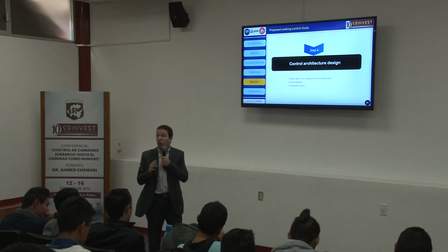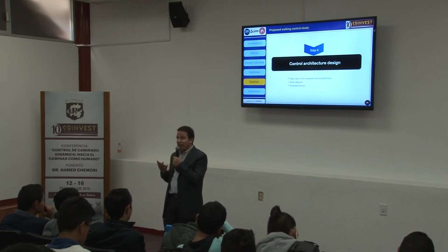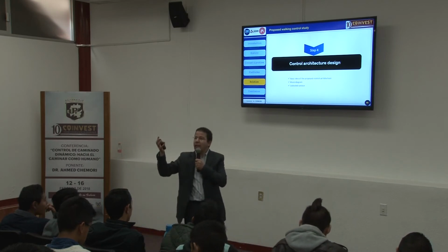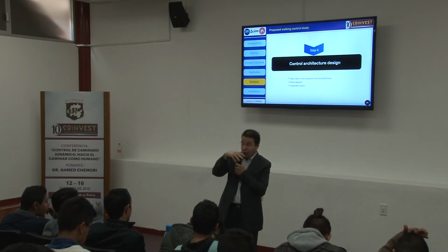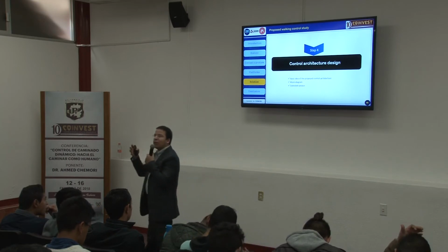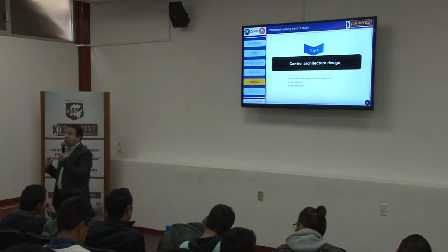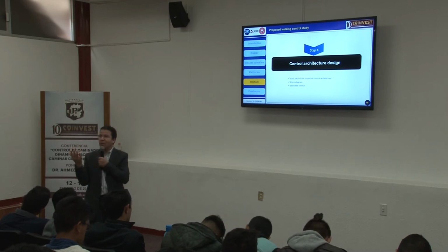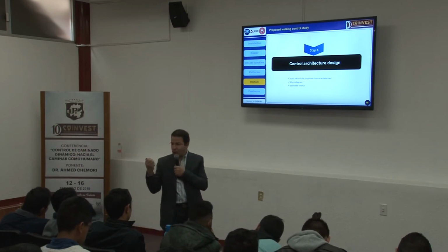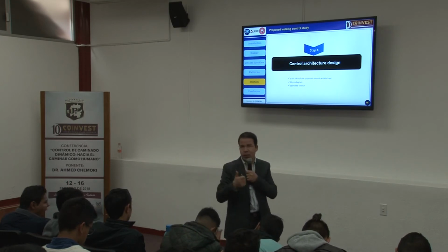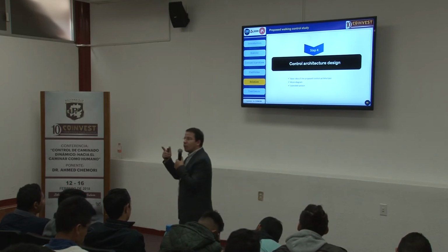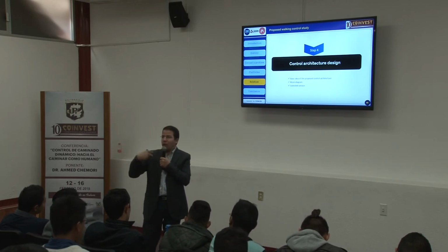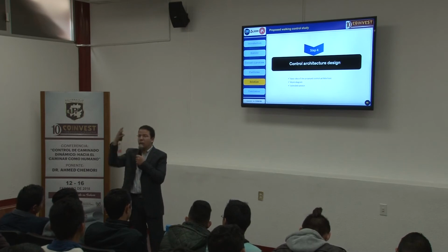There are also other solutions based on the human data. So they do the same human walking study, they get the data, and they try to use the data on the humanoid robot. We have different problems in this case, the problem of scaling, because the size of the human and the size of the robot are not the same. So you cannot apply directly the measurement on the human to the robot. And also another very important thing is the number of data. If you use all the joints, you will have a huge number of data to be applied on the robot.